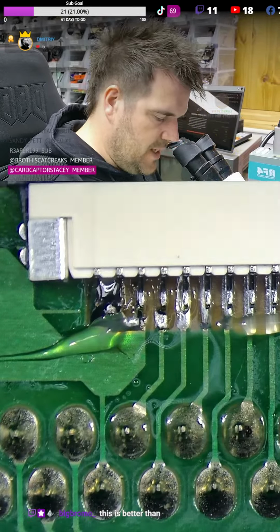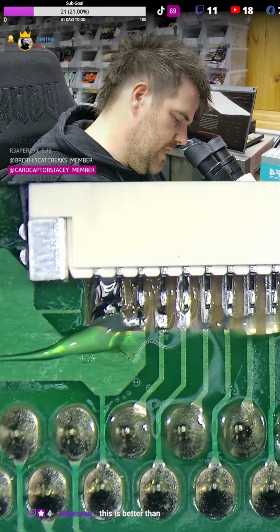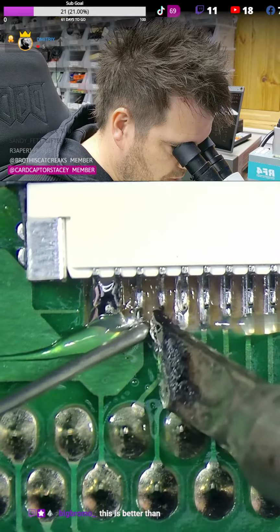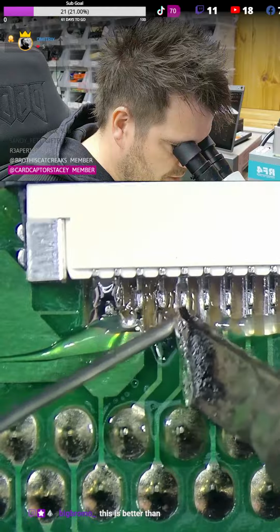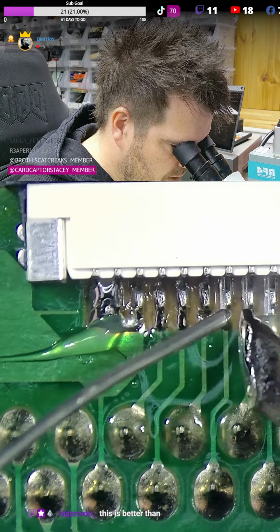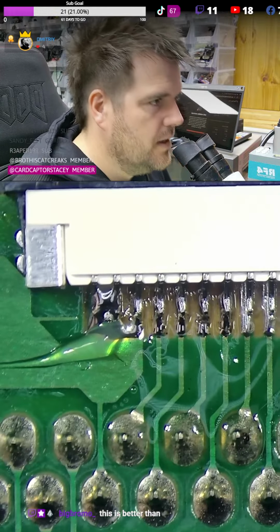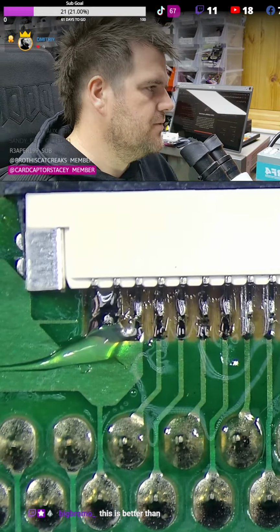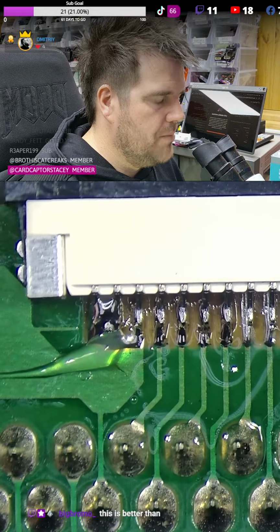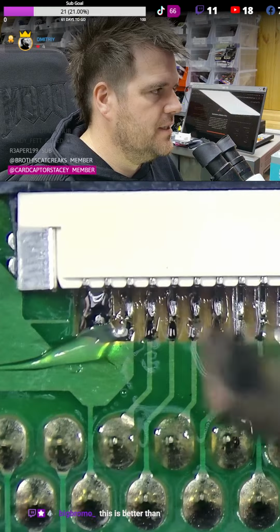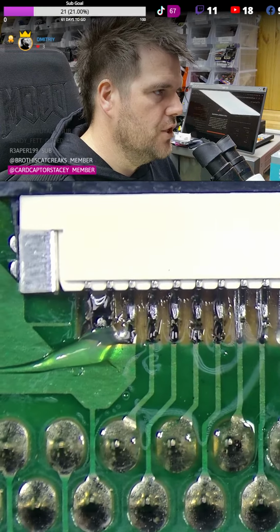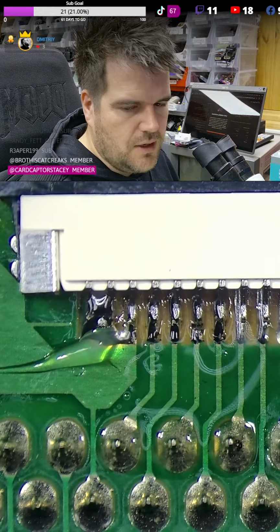So I'm going to go down here now, and what I was saying is people trying to solder these will probably just go on one pin at a time like this, and desperately try not to touch other pins, going down one pin at a time. And you can do that, but that's what typically leads to people not getting enough heat on the pins because they're scared of touching the pins either side, and they'll normally use a smaller tip because they want the tip to not touch.